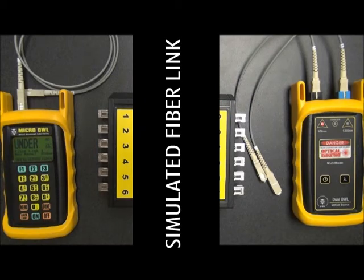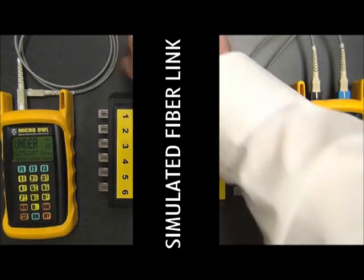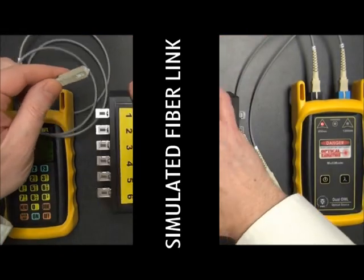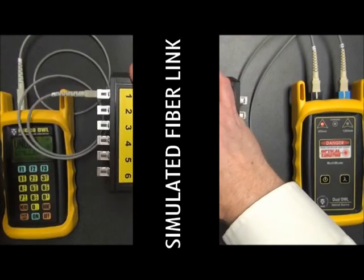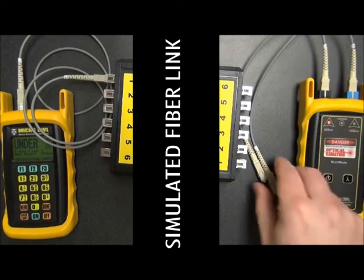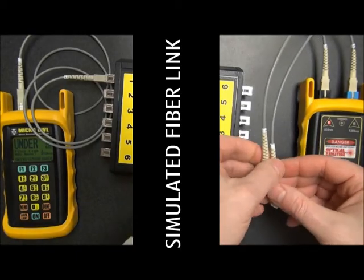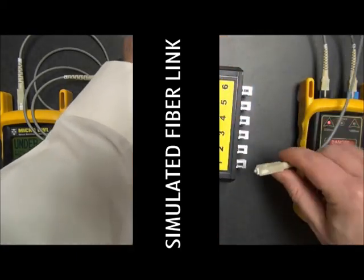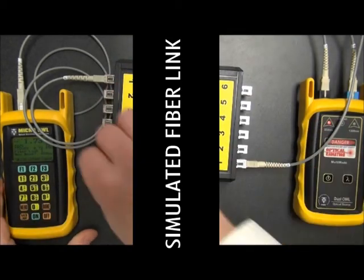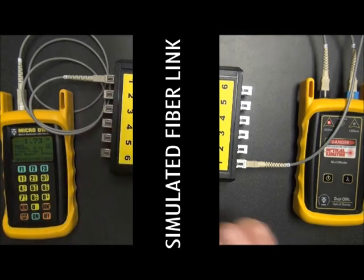Now, the first thing we need to do is connect into port number 1. Okay, so that's usually where you start. You start at port number 1. So we're going to connect in on both sides. Okay, remember that we're going to be using the 850 nanometer reference cable here. So we need to locate that and connect in. And as you can see, we have a reading show up on the screen.